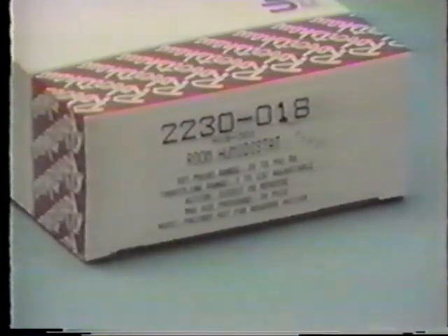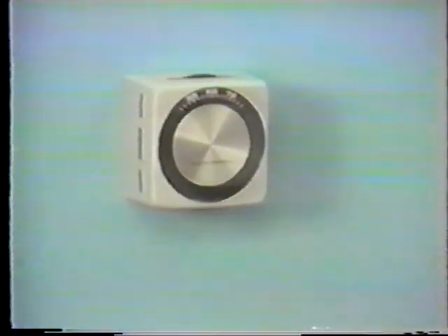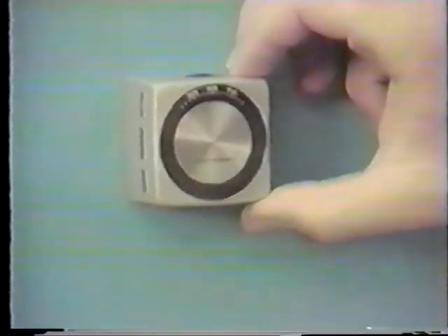The next controlling device we will talk about in this section is the pneumatic room humidistat. The pneumatic room humidistat is also a proportioning type device designed to control pneumatic valves or damper actuators on heating or cooling coils, humidifiers, air washers, and other humidifying or dehumidifying equipment to maintain a constant relative humidity.